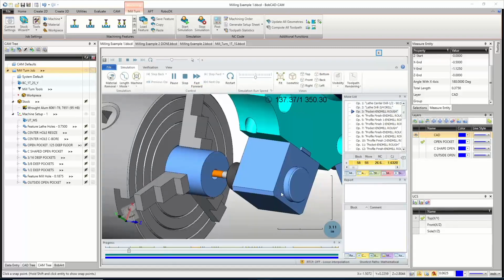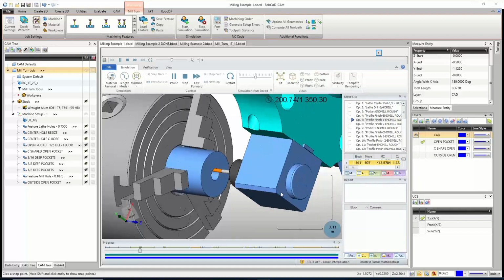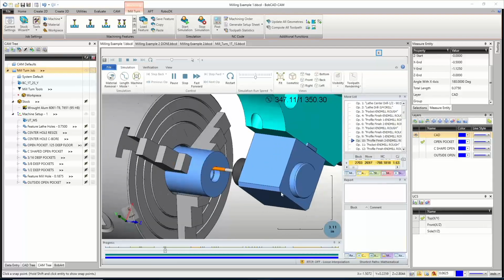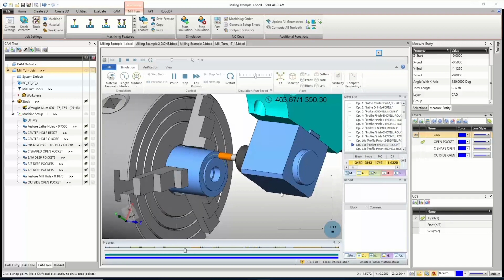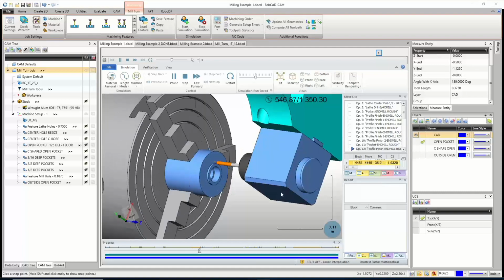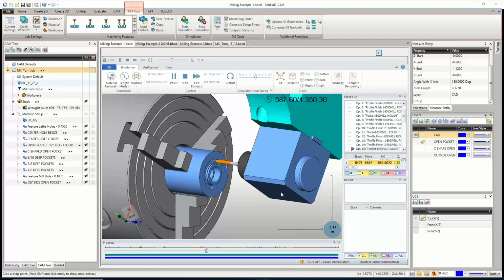And there's our center drill and drill. Now that we have everything going in the right order, it should come out quite a bit better. There's our finish for that, 3 finish passes. And we open up that counter bore. We could use a turning tool to do some of this work as well. Same with that right there. I could have turned that in with a CNMG and then maybe done just a cleanup pass with a sharp cornered end mill. Just depends on how you want to set it up.